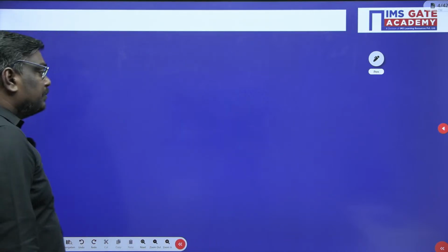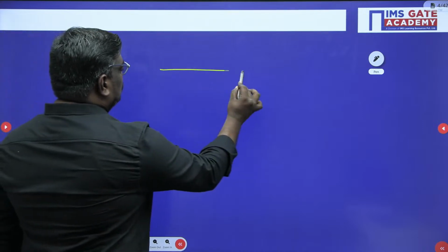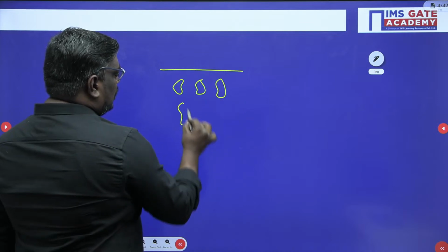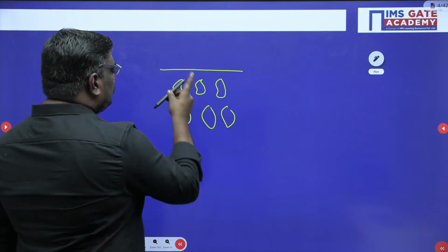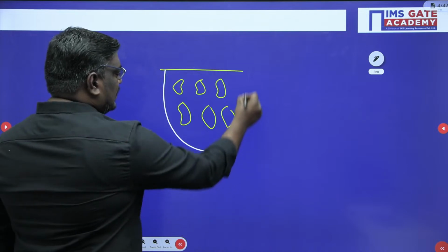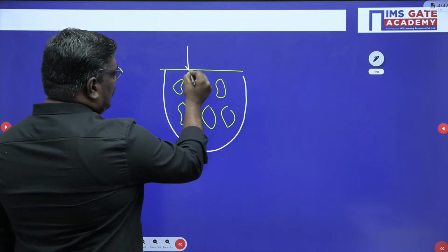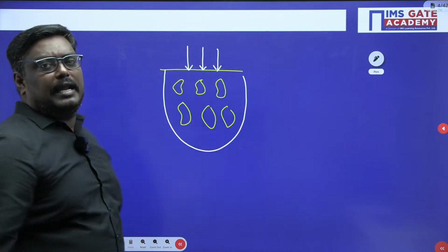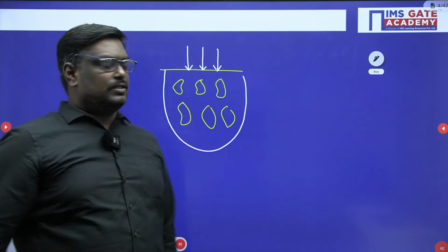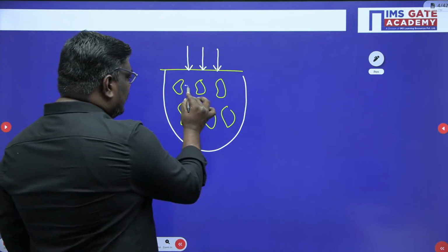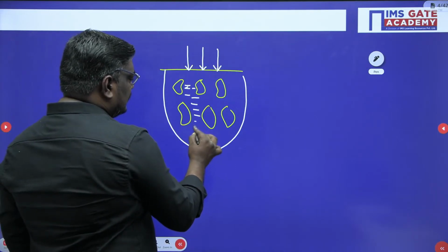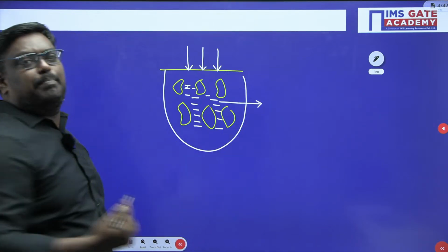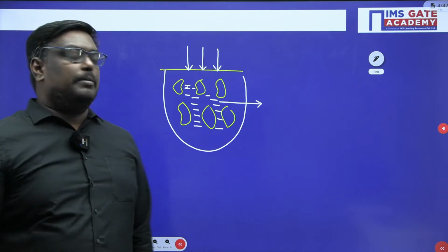Gagan, are you following? Now my dear students, suppose I consider the soil particles here. If you consider this as the entire load and this as the entire area, the load upon the entire area will be the total stress. But in this, there will be some water filled in the voids. The stress due to water, or pore water, is nothing but neutral pressure.